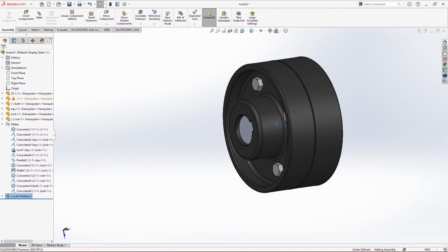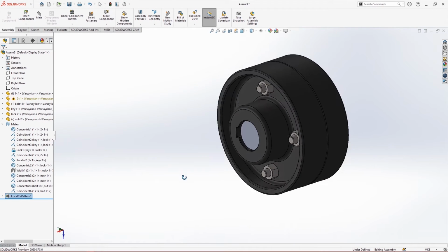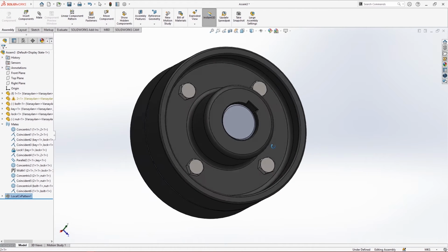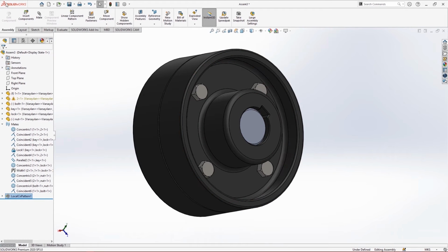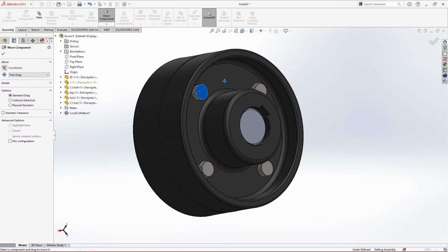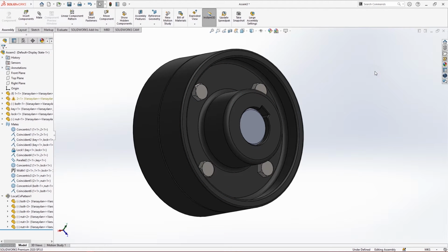So you can see this work is completed. Basically it is done, and we can check using the movements if there is something like that. Now you can see it is still rotating. That's why we see underdefined here in the bottom. So we can also lock the rotation, but for the time being it doesn't change anything.